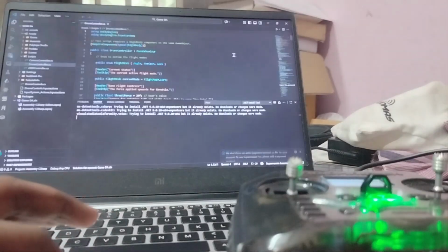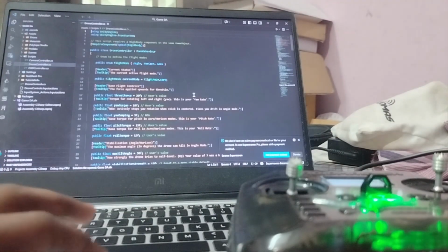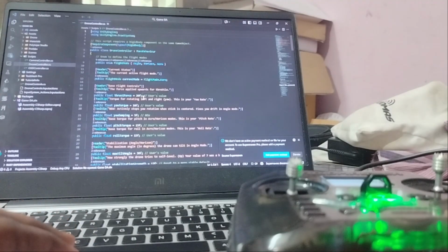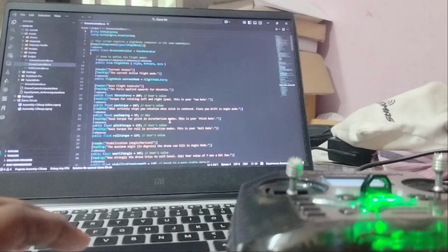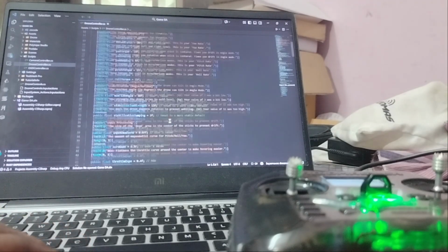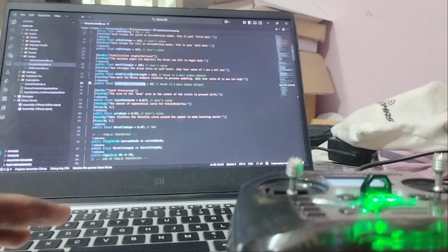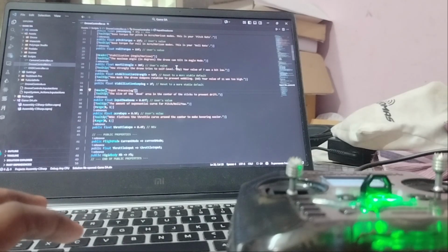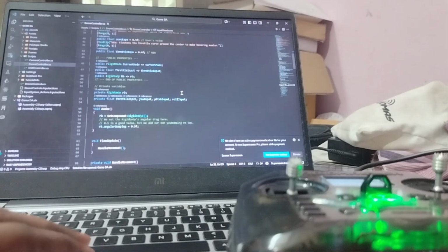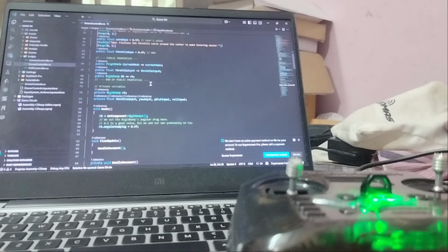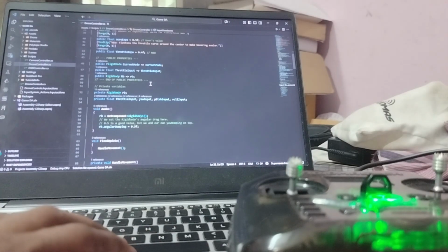So if I open the code, this is the drone controller, which has all the parameters defined, like the thrust force, yaw torque, all the configuration which is required for the drone, and dampening strength and stabilization. Stabilization strength and stabilization damping act as the P and D values in the PD controller, and I also used a rigid body component on this drone so that all the other forces like gravity and air resistance are applicable to our object so that it mimics the real world drone.